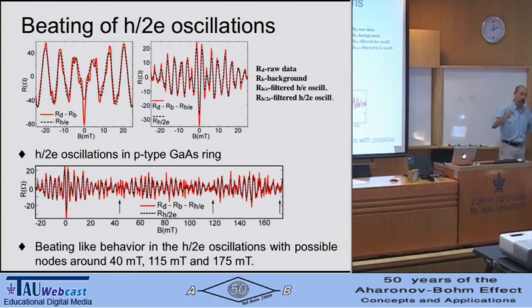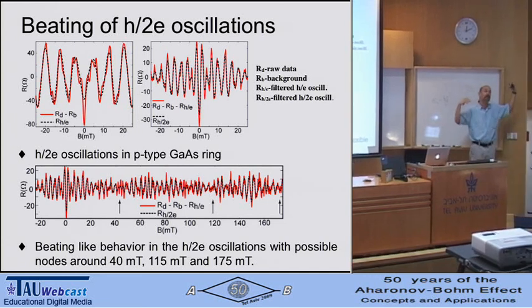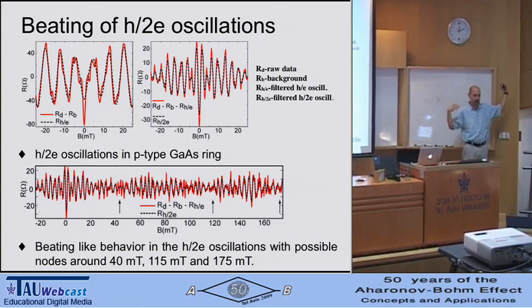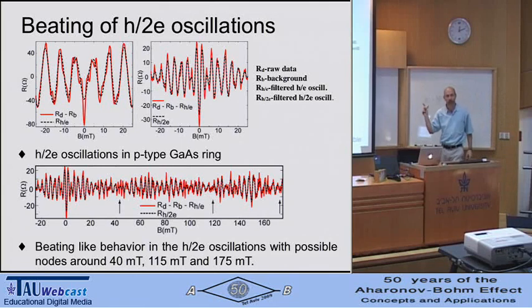It's another very good question. So if you basically go through zero bias, then you're limited by thermal excitations. So you have thermal tunneling. Now the question is, if you want to go to the linear regime or nonlinear regime, you have to apply an even larger bias voltage. Now, for the system that we're looking at here, it's again related to the bandwidth of the detector. We can only measure small currents. If you want to go to the nonlinear regime, you need large currents. And that's not possible with this method here. So you need to go back to conventional noise experiments.